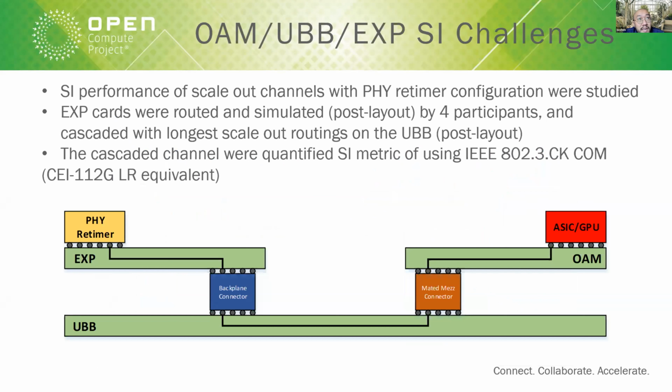After the PHY retimer, again, you can terminate as QDD or OSFP 800G in a front pluggable. That's not our focus today. Our focus is from the LR retimer all the way to the ASIC. For this one we also did the layout by leveraging the engineering effort from 4 participants, which are the 4 major connector participants in the market.